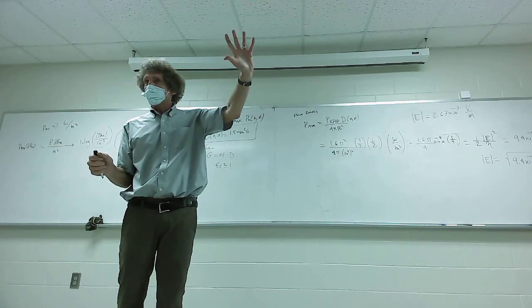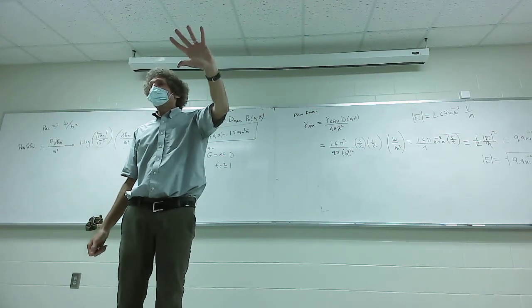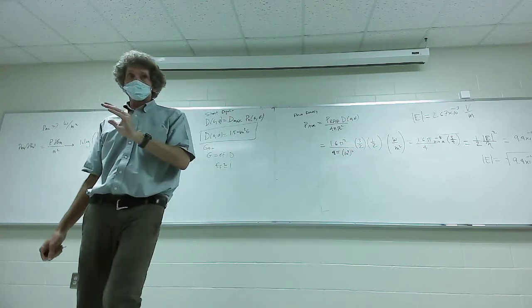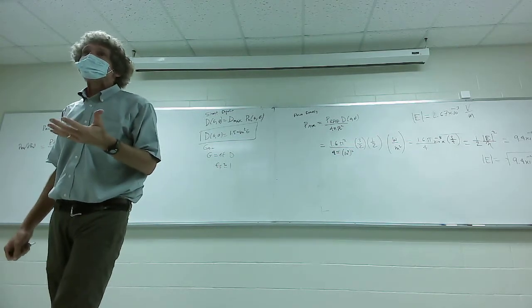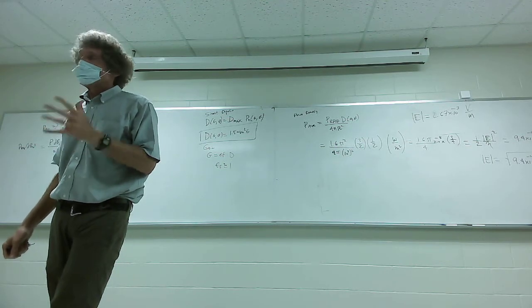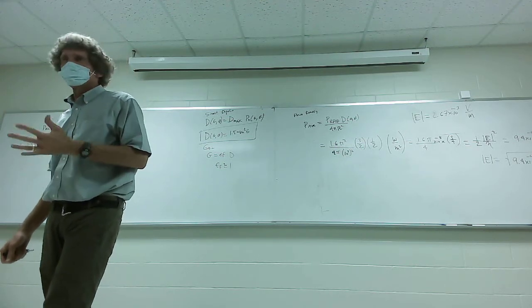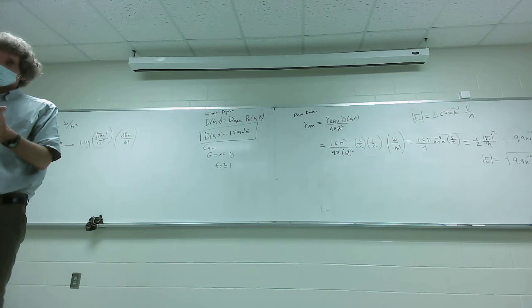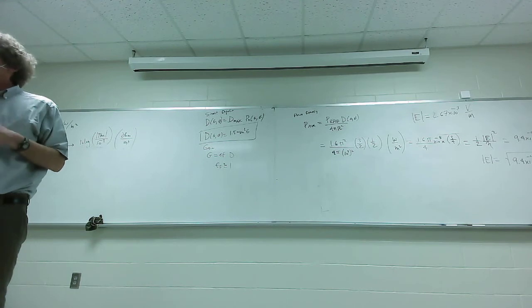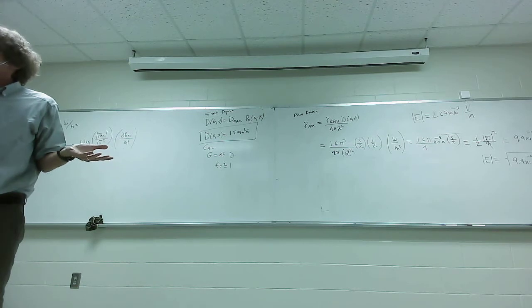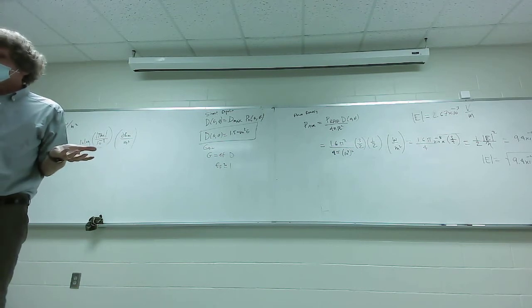On your cell phones, I think just about all of them still, you can look up for the type you have how to find out what the power density is there. They'll show you either the power density or the receive power, one of the two, and the receive power will be in dBm. Anybody want to take a guess at where the threshold is of what you can actually see on your phone? If you want to know the strength from a cell phone tower nearby, for whatever phone you have, you can do this. The threshold usually is about minus 90 to minus 100 dBm. When you get below that, good luck. That means you just can't pull the signal out of noise. It's just impossible.